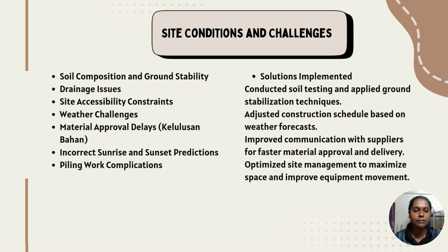Then the piling work complication, where we encountered hard soil layers during the piling for the astaka, which is the grandstand, and then the backstop netting. This required adjustments in the piling method and the use of additional equipment.